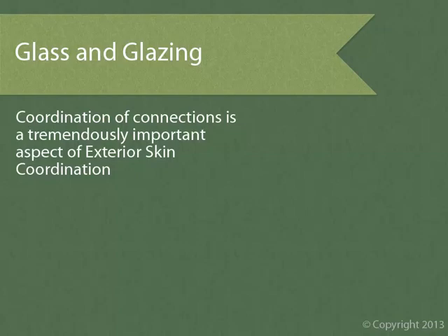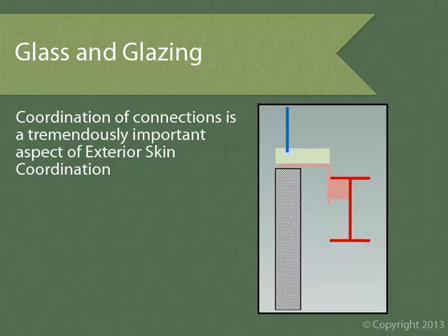If these modifications are a result of the general contractor's lack of coordination, the general contractor could end up paying the bill for it. For this example, let's expand on the previous illustration with the assumption that the glass subcontractor is going to provide a steel angle support for their curtain wall. In this scenario, we actually have two conflicts, so let me start with the first one. Note that this angle is designed to be continuous, not intermittent.